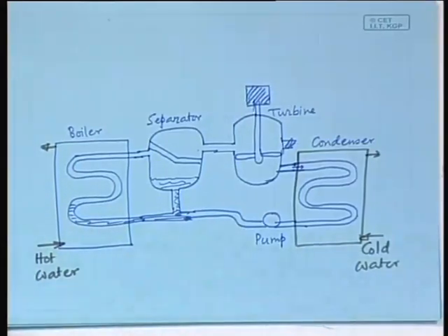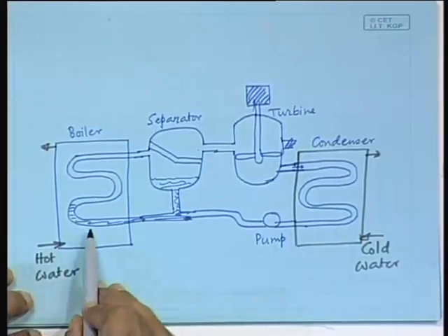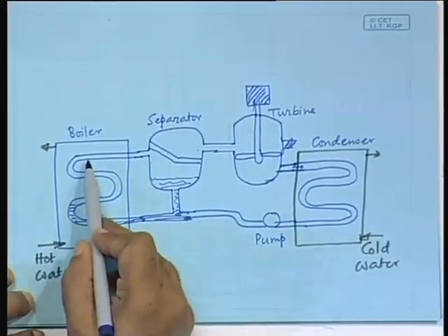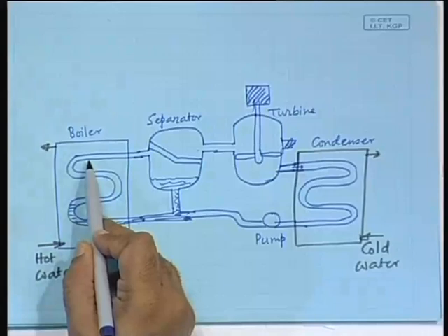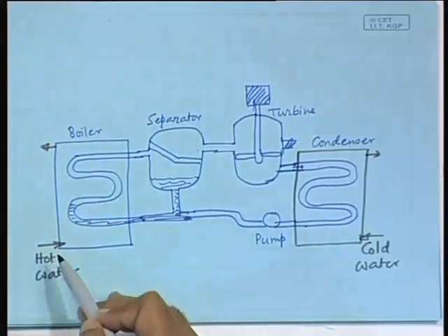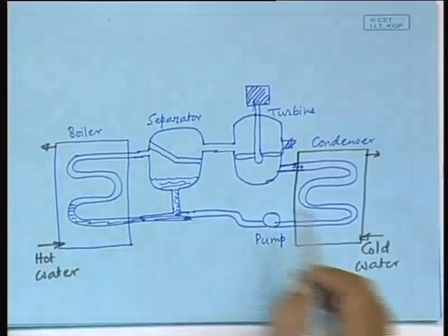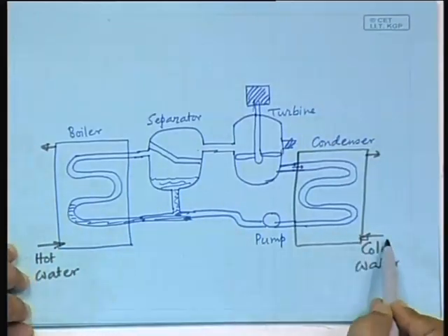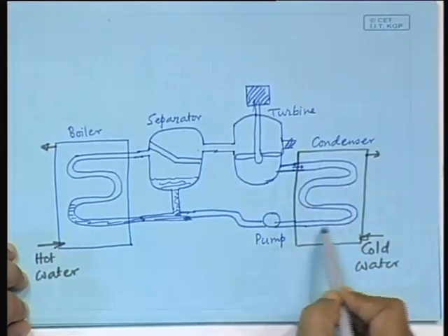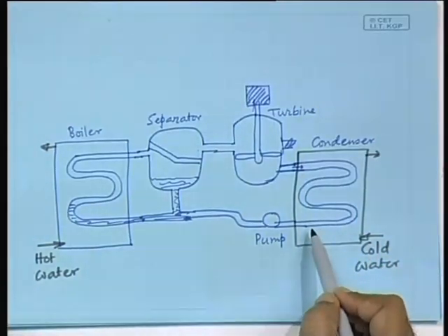So, can you see that because the hot water is not directly in contact with the principal fluid, there is a heat exchanger. So, obviously, the temperature of the principal fluid at its peak will not be the temperature of the hot water, it should be slightly below. Here also the cold water temperature can be 10 degrees, but the temperature to which it can be cooled will not be 10 degrees, somewhat higher.